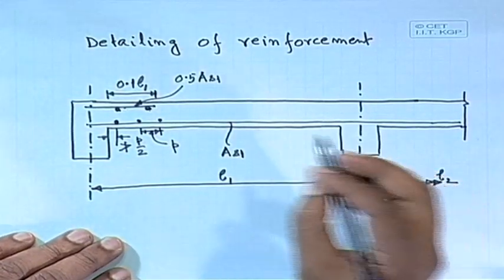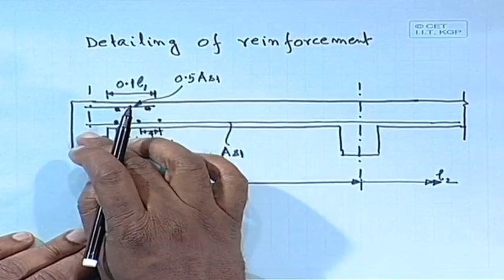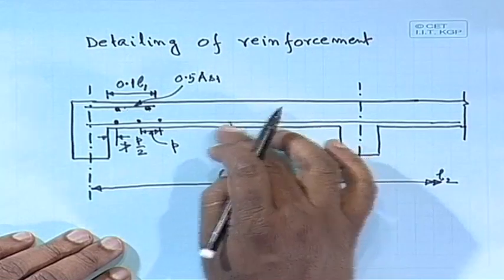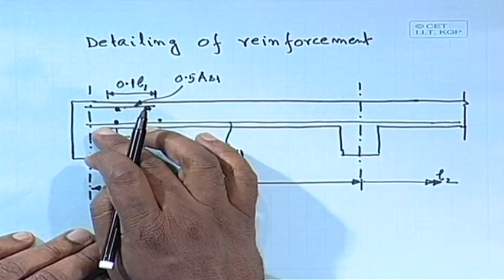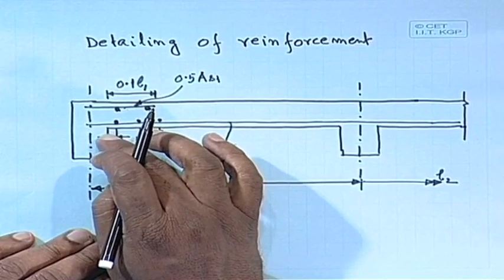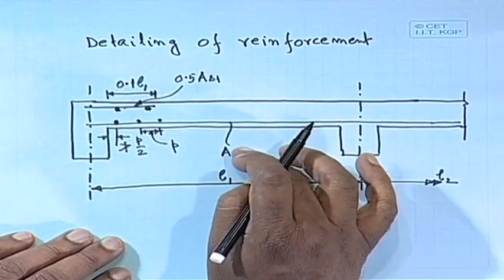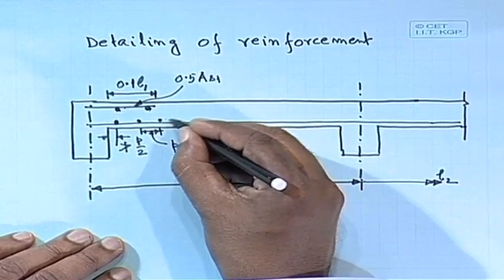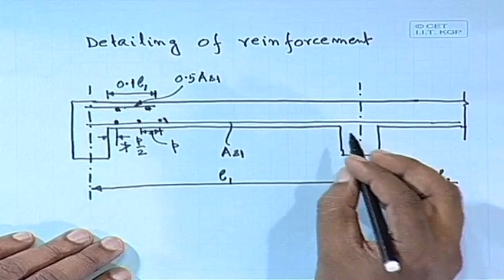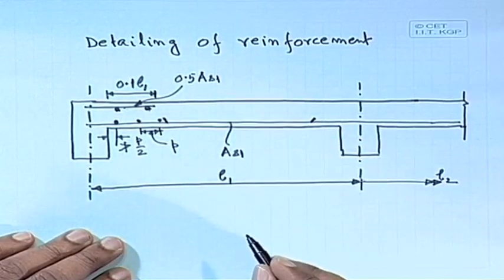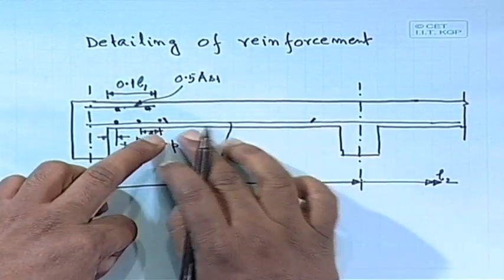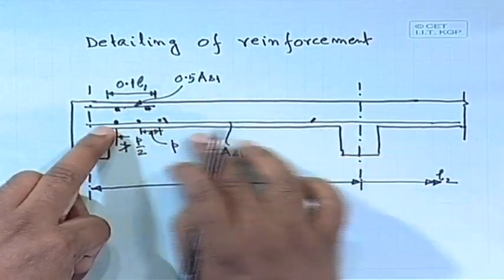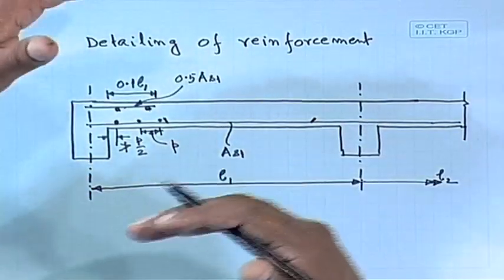Number 2, in the middle here in the support we do not need the span steel, whatever area of steel we have got in the span, because the moment is less at the bottom here. So, we do not need that much. So, what we shall do is curtail the bar somewhere here, and similarly curtail the bar here. These are the bars we are specifying, that means one bar of this length, the other bar will go. So, that way we can provide the bars alternately.